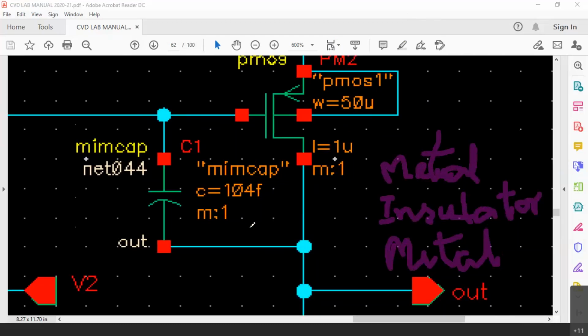It will give you a beautiful square or rectangular structure where one end is metal 1 and the other is metal 2. Now you will have to connect metal 2 and metal 1 along with wires, because here the gate is polysilicon, and the drain is P implantation inside N well. You need a wire from metal 1 or metal 2, depending upon which side you are keeping.